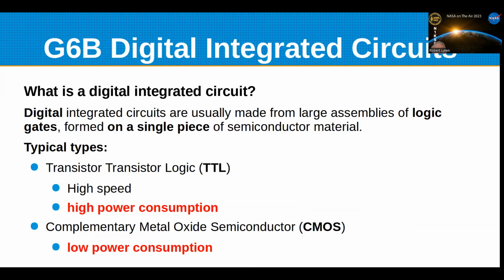So when you got to doing portable devices like cell phones and things like that, then they started going to CMOS circuitry, complementary metal oxide semiconductors. It has much lower power, and they can operate at lower voltages. TTL is typically 5-volt range.